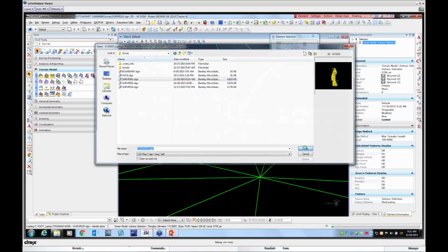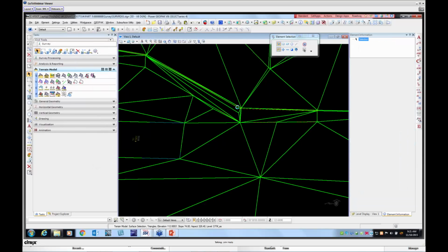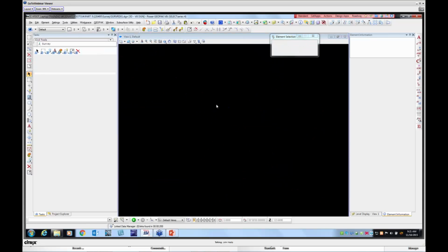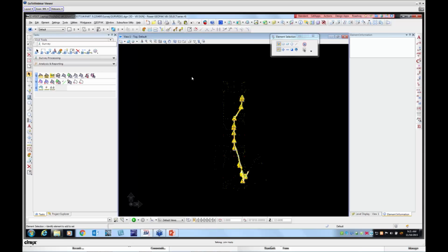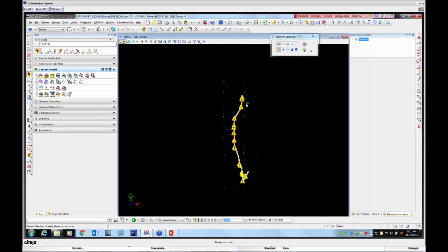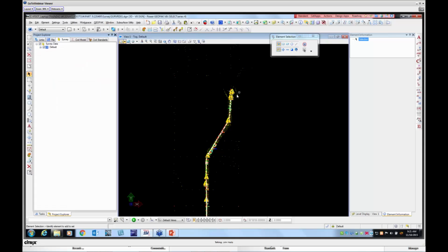This is one of the raw files I opened last time and did a little teeny bit of cleanup on, but I want to show you a little bit more of things we can do for cleaning up a file. If you remember from last time, the exclamation marks mean that there's a warning that there's a problem, usually a feature definition issue.